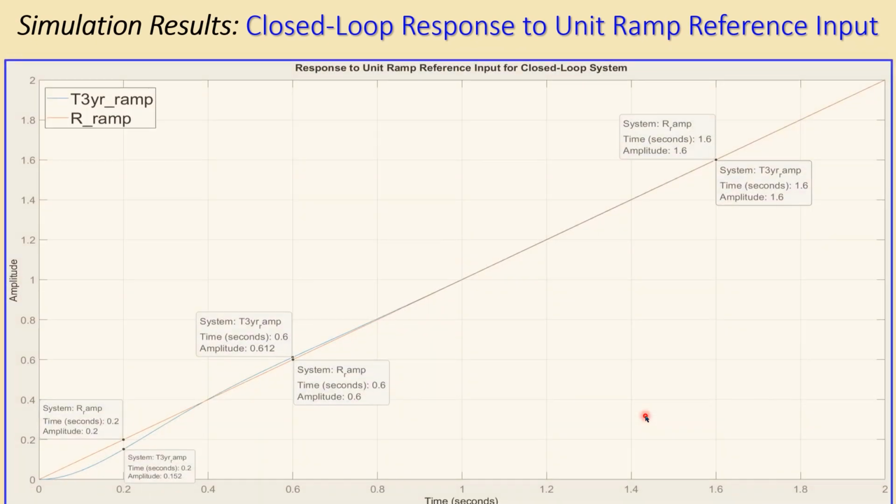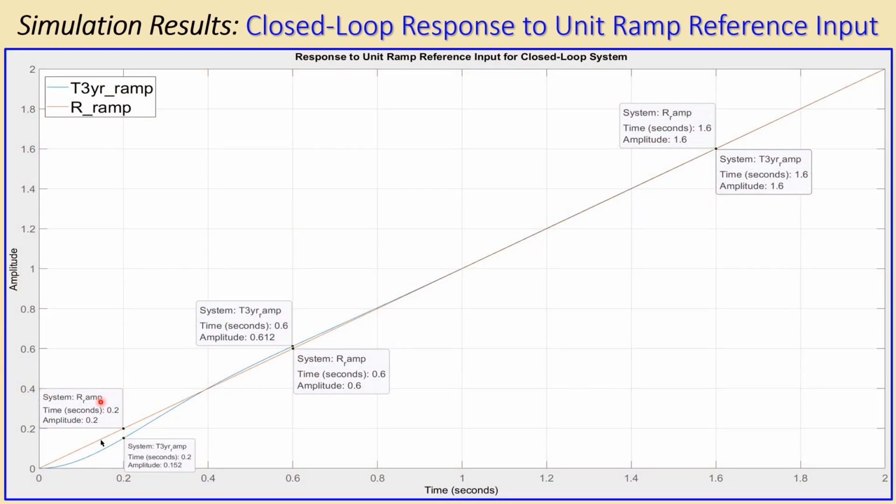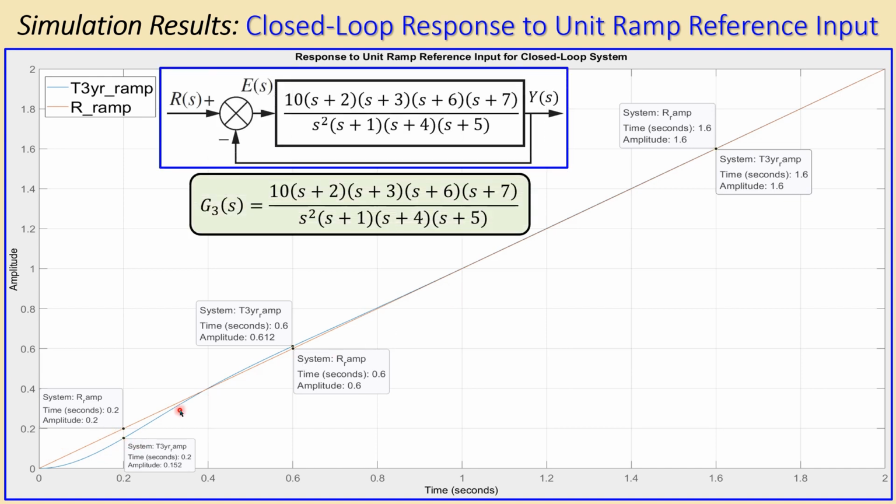Okay, now also looking at the unit ramp, and you can see from here, again from the start, I have again plotted the orange line, which is our input, and the blue line is our response for this configuration. And again, at the beginning, you sort of have some error. So you might say, okay, there is some error, but if you look at values later on, so that's actually the steady state condition, of course, you will see that this error will be then 0.